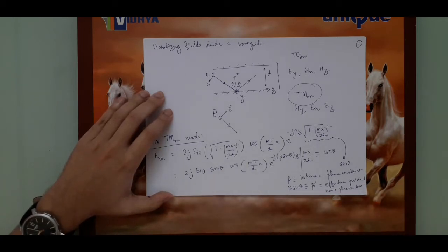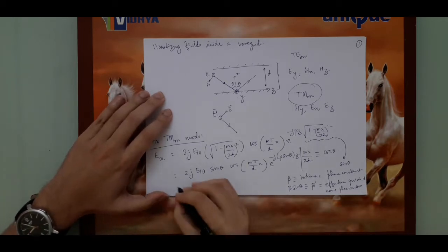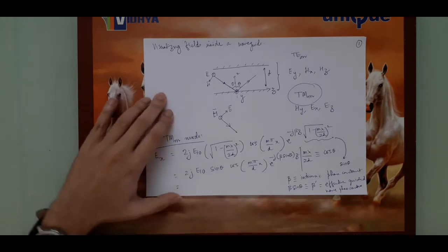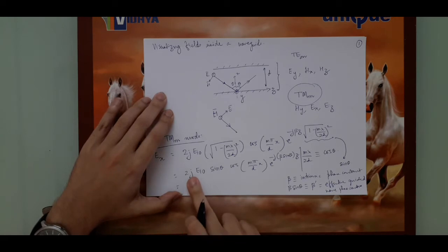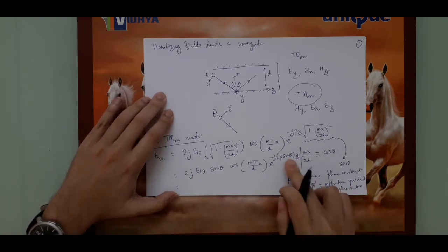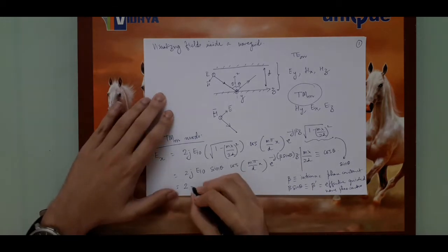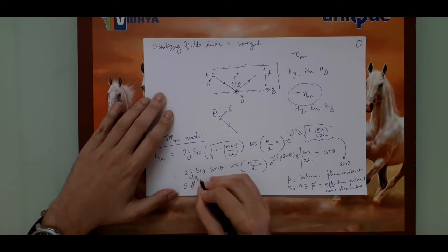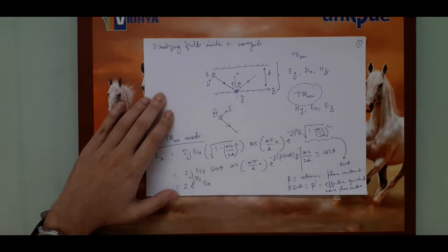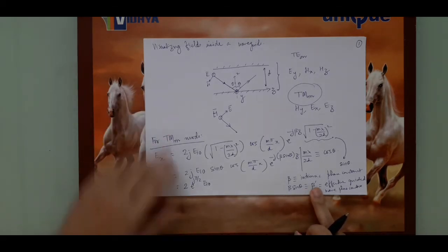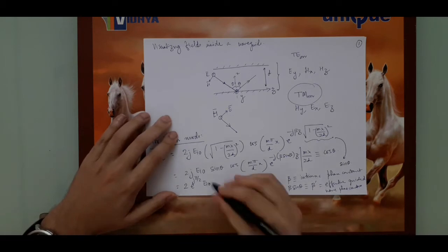So therefore now what I can do very easily is write this j as e raised to j pi by 2, a phase term, which I can absorb over here. So this is 2 e raised to j pi by 2 ei0. Now sin theta I can simply write as beta prime by beta, because beta sin theta is beta prime.